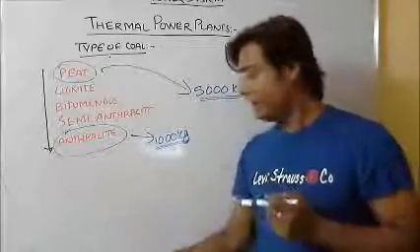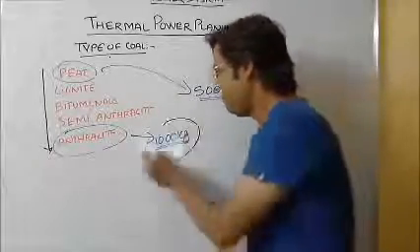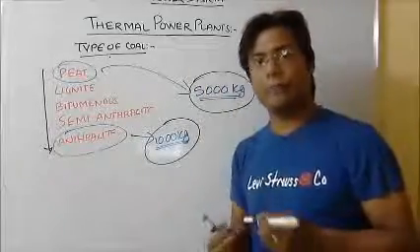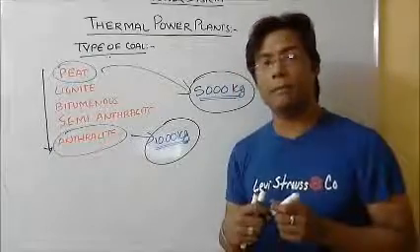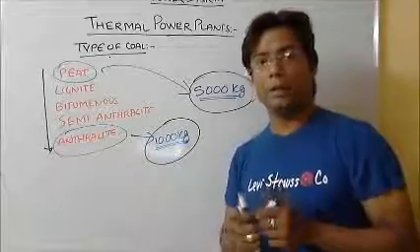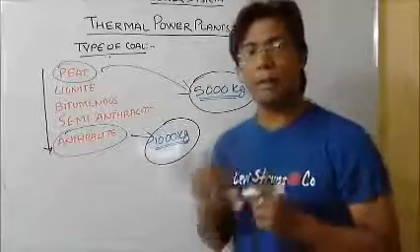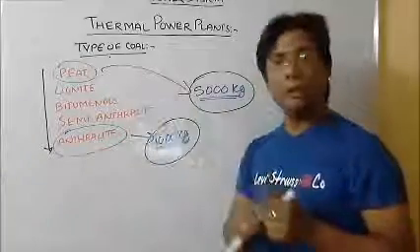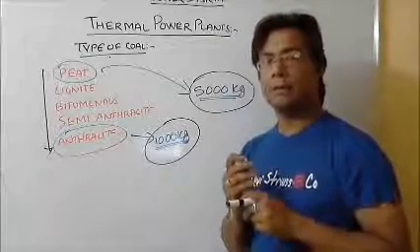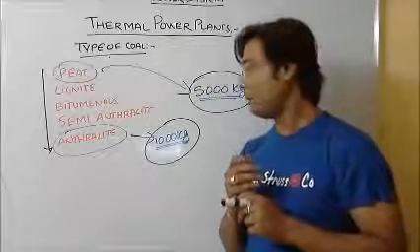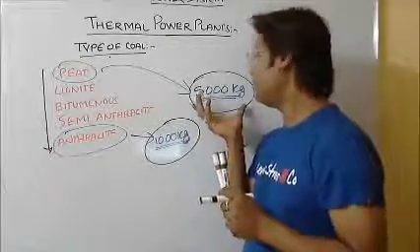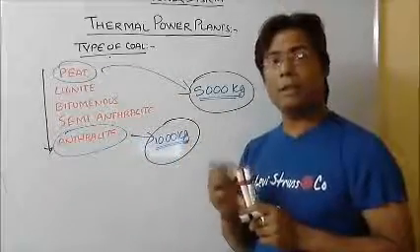So one can directly understand this thing, that the transportation of 1000 kg will be less, and the transportation of 5000 kg will be more, wherever I am transferring this much of coal. If I am able to transfer 1000 kg of coal of anthracite type to the coal handling plant, I'll be producing that much electricity which 5000 kg of the peat will be producing. This is just an example so that we can understand how the transportation of the fuel changes the efficiency of the total power plant. So coming back to the discussion, if I'm carrying 1000 kg of the anthracite to the station, or I'm getting 5000 kg of the peat to the station, both are giving the same heat.